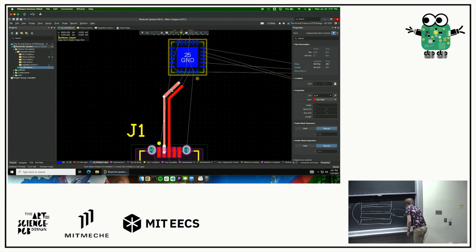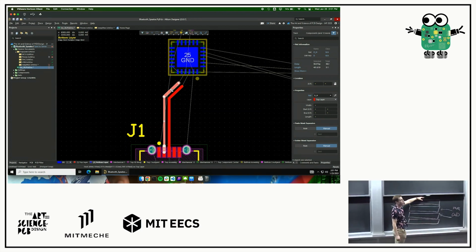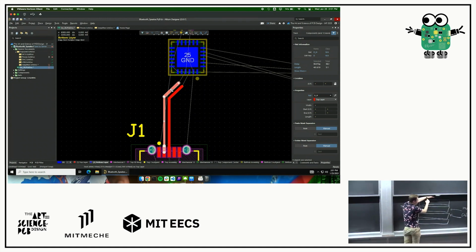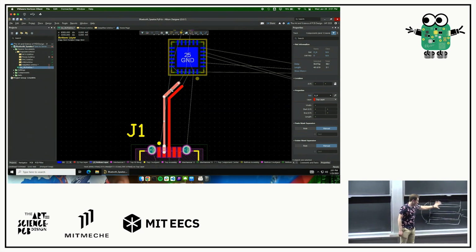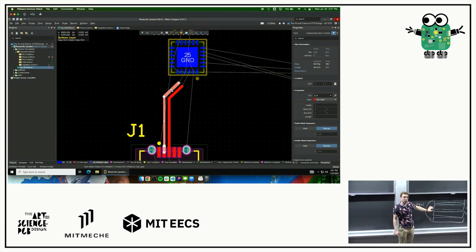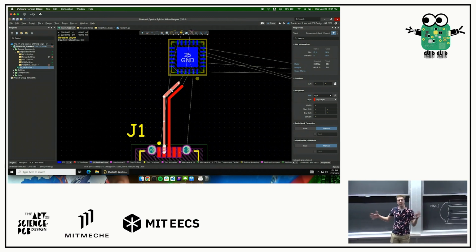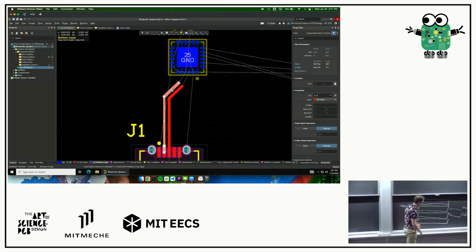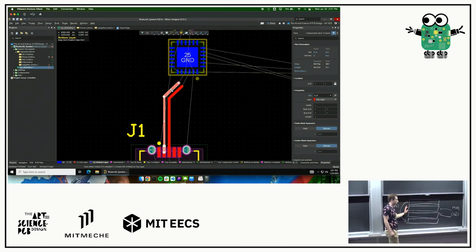And what this lets us do is it's a convenience thing, right? If we have some part on the top here that needs power and ground, we just drop a via next to the power pin and next to the ground pin, and there we go. Make sure our bypass caps are nice and close, but that's the setup for it. This is a 4-layer board, right? But we're asking you to make 2-layer boards because we want to tame the complexity of what you're working on. So a lot of times what we'll settle for is instead of a power plane,